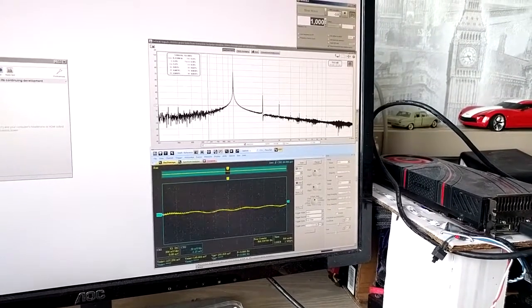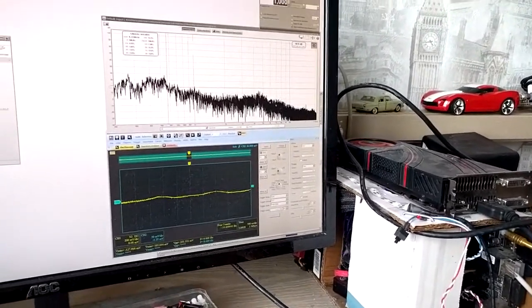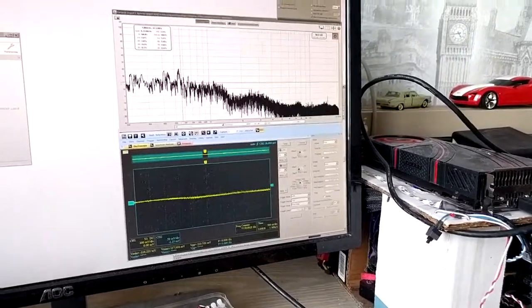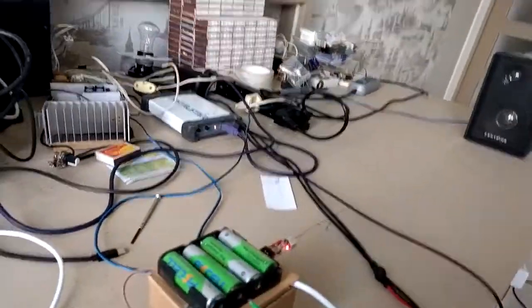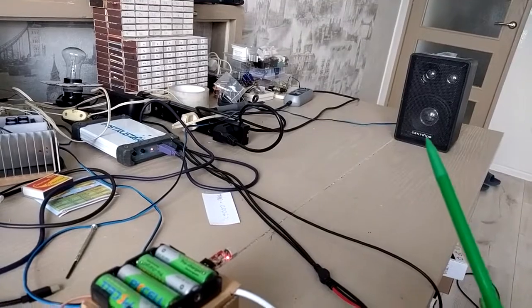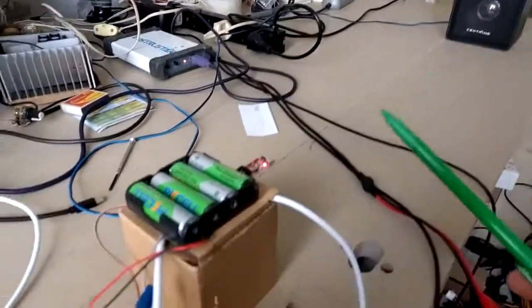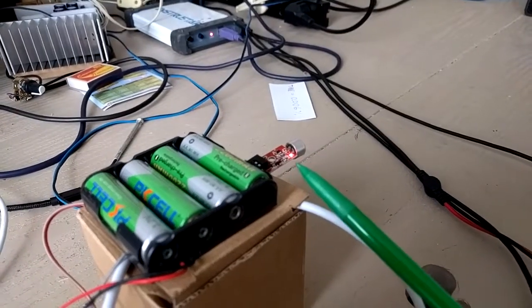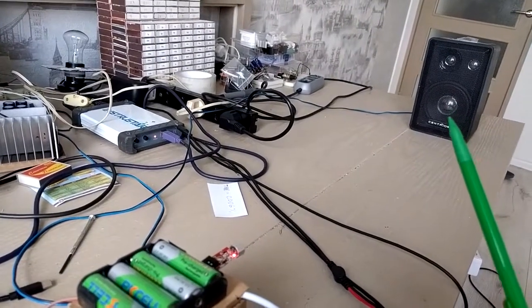To conclude those results, what we see is that if we increase the sound level, we're going to see an increase in total harmonic distortion coming from the speaker. However, we should note that we have to decouple this distortion. One source of distortion is the speaker itself, and the second one is the microphone. So we have to minimize the distortion caused by the microphone so that we can measure the actual distortion from the speakers.